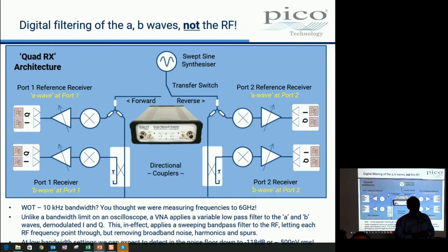Now the importance of that is if I select things down to, say, 10 hertz, then I can't see changes that are happening quicker than 10 hertz. So if I was drawing this gain plot as a line, isn't it? And if it had information on it going up and down that was faster than 10 hertz, I wouldn't see it, right?